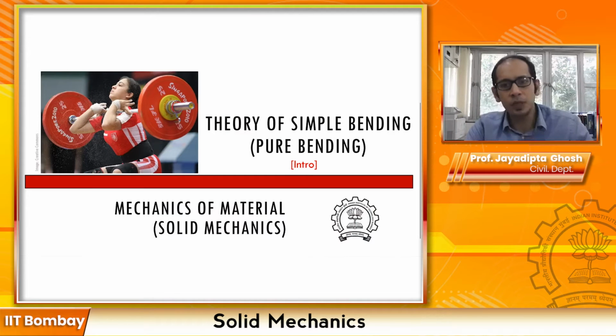Now, you might be slightly misled by what we mean by pure bending or simple bending. Well, it of course means that you're removing the effect of shear while you're calculating the section displacements and the section deformation. So you're purely focusing on the effects of bending, the pure bending.